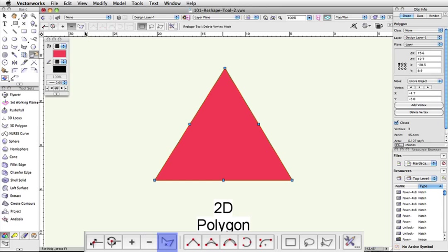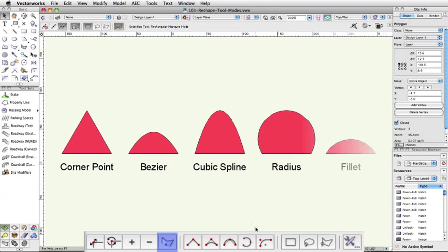Hide or show edges allows you to hide any edge that you click on directly. If you click on a corner vertex instead of an edge, it will hide the next edge after that corner in the shape. The reason this mode exists is simply for appearance. It does not remove the vertex as the delete mode does. It simply hides the line. This allows you to make a gap in a property line, for example, or hide the edge of a space so that it does not cross an open door threshold in a confusing manner.